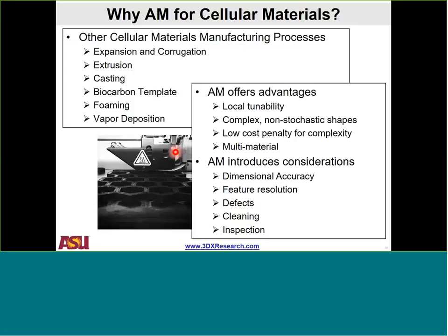So why additive? And there are some advantages, and I think most of you all that work in additive are familiar with these. But one, maybe the biggest one that I like to think about, is the ability to perform local tuning. And I showed those optimization of parameter examples where you can vary thickness locally. The other one is you can develop complex non-stochastic shapes. So with the foaming process in particular, you don't have as much control, and you end up with a stochastic shape, like a bunch of bubbles trapped in a fluid.